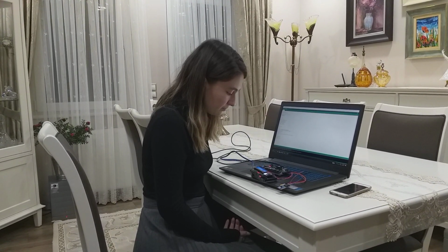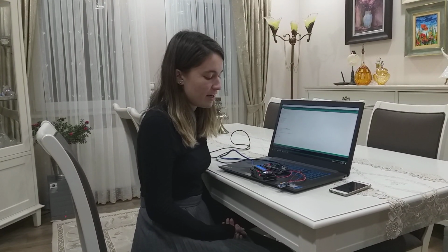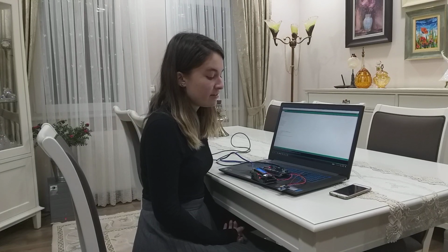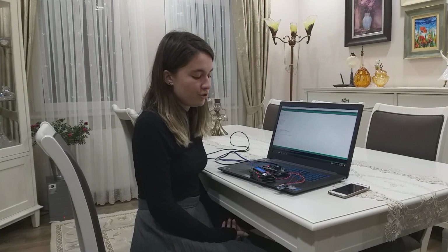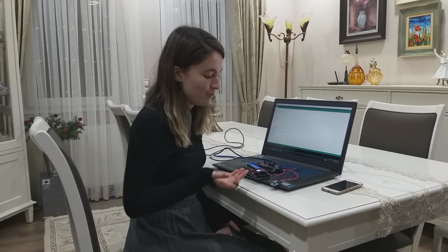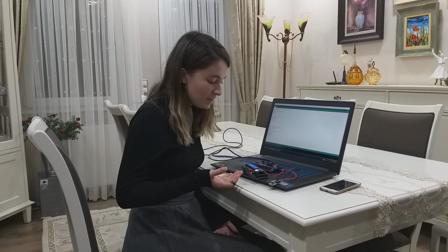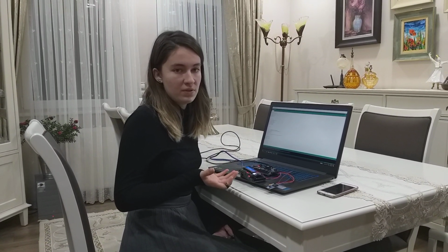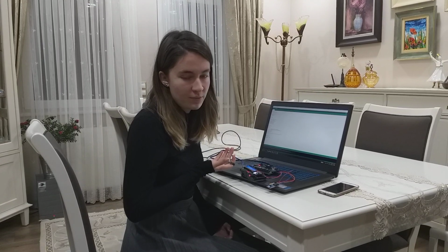To begin my project, I first used the PMod Mic 3 module of Digilent. This module enabled me to get the sound data from the environment in an analog format, and to transform this data into a digital one, exactly into 12 bits, using its analog to digital converter. And this enabled me to get the sound signals that I need to use in my project.